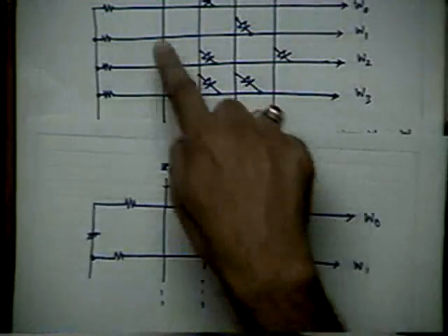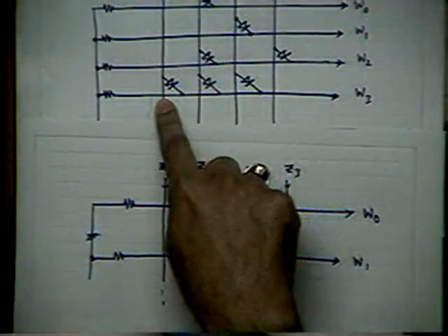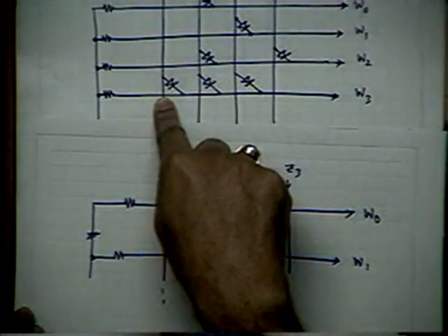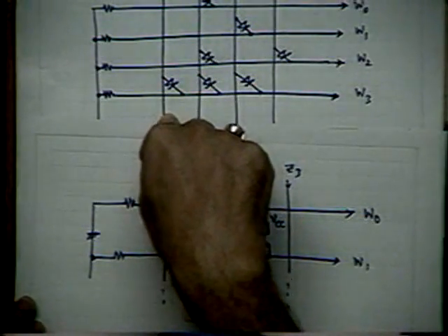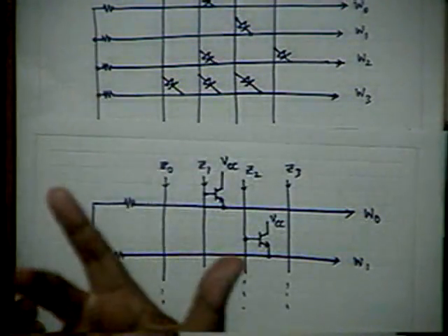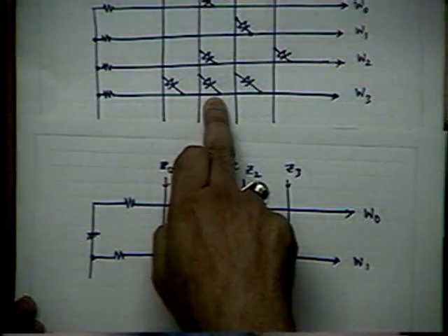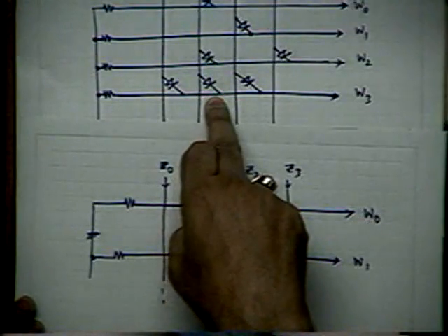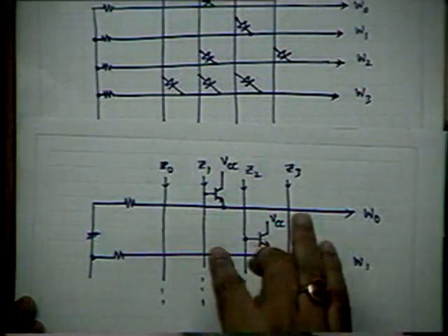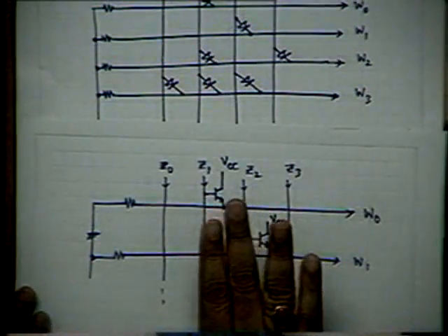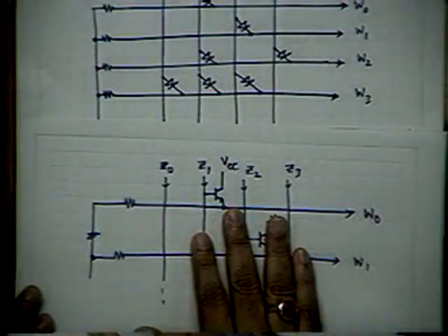Therefore, be it this one or that, always you are making transistors here. At the intersection of each node, below each node, there is a transistor. So space-wise, there is no benefit here with respect to this. The only thing is, here you are using the transistor as a diode, and here you are using them as transistors. And therefore, this one definitely is a much superior step forward for the realization of bipolar.